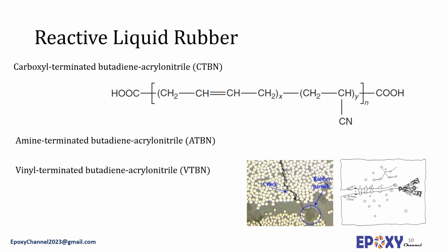The formation of a fully dispersed phase depends on a delicate balance between the miscibility of the elastomer or its adduct with the resin hardener mixture and appropriate precipitation during the crosslink reactions. The advantage of this toughening process is that the high modulus and Tg of the epoxy resins are not sacrificed.